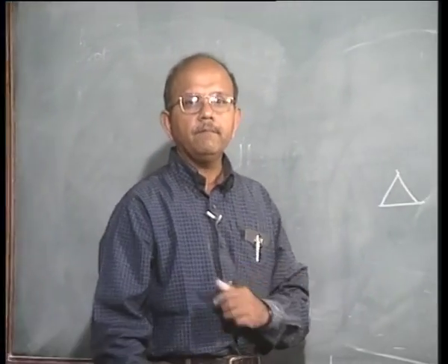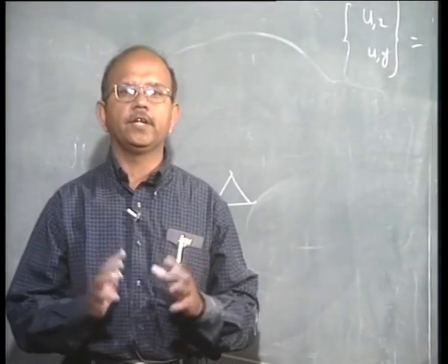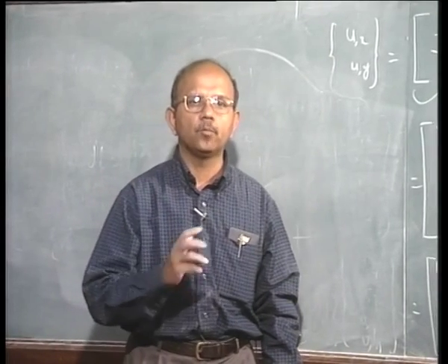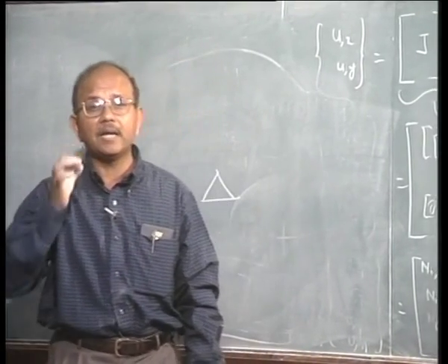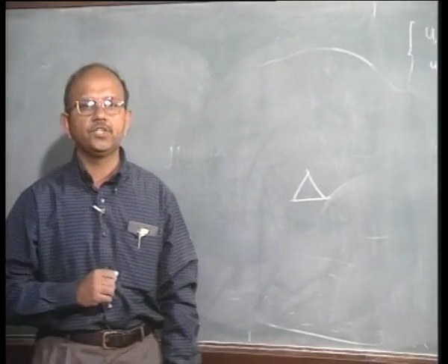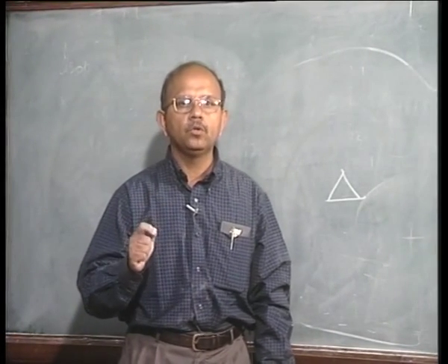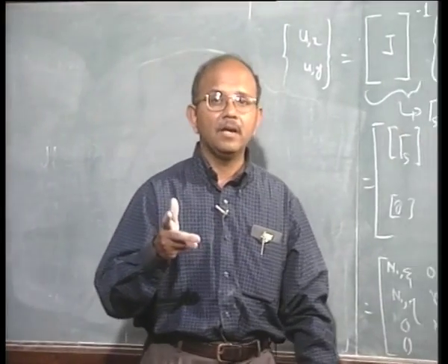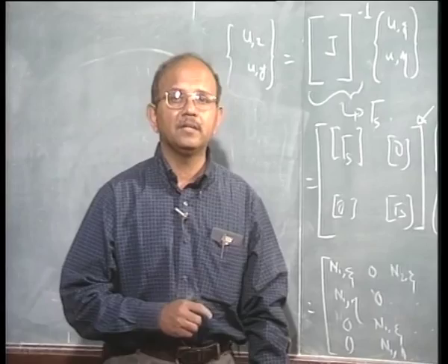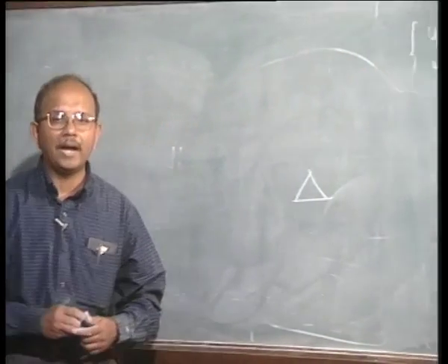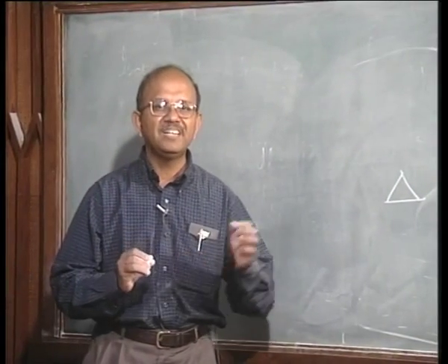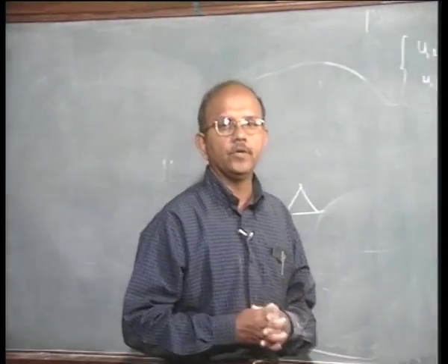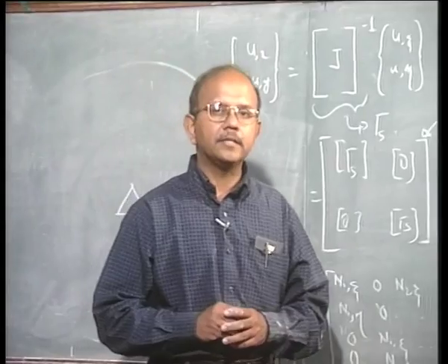Today there are a lot of mesh generators which can do quadrilateral elements, so there is no problem, but hardly any mesh generators can do what we call a hexahedron element, and hence it becomes important that we know how to handle triangular elements. Basically there are two ways in which triangular element stiffness matrices are determined.